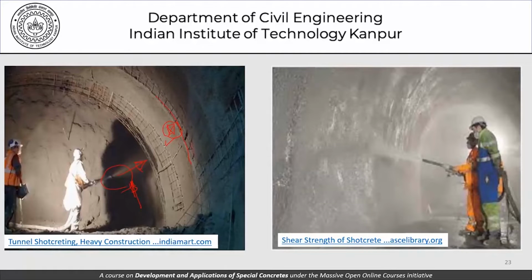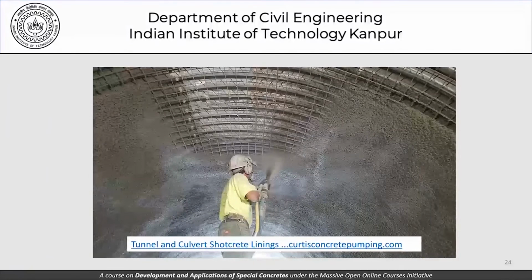We will have another couple of photographs about shotcreting, and there are a couple of things which you would learn. Here is another kind of shotcreting going on, where the shotcreting is on the top. That means the shotcreting will happen from the bottom, which means there will be a lot of rebound. So these are things which we can discuss during the shotcreting methods and the proportioning of shotcrete, because we need to have a certain type of property and so on, which is fine.